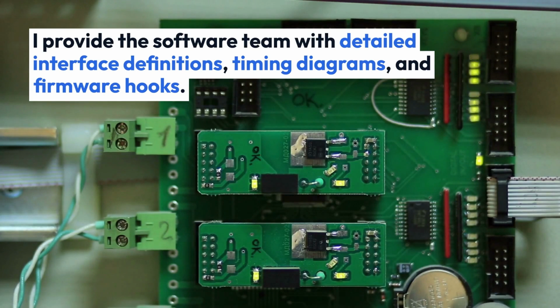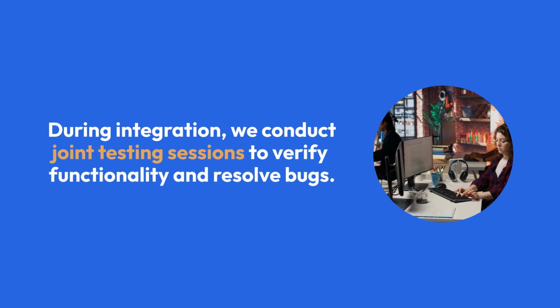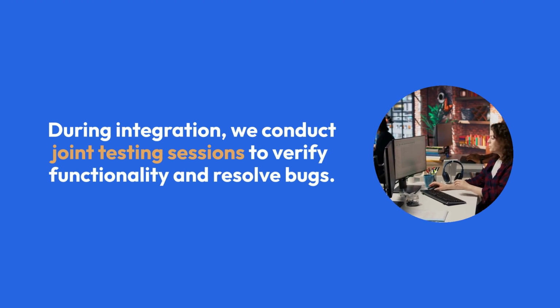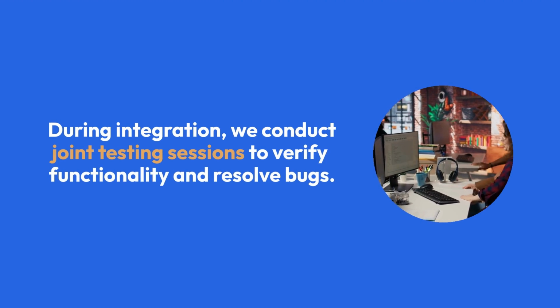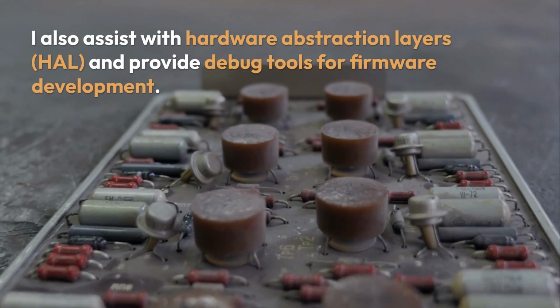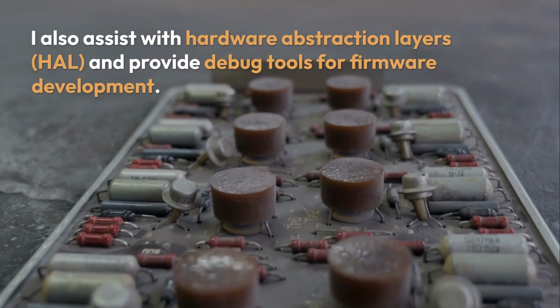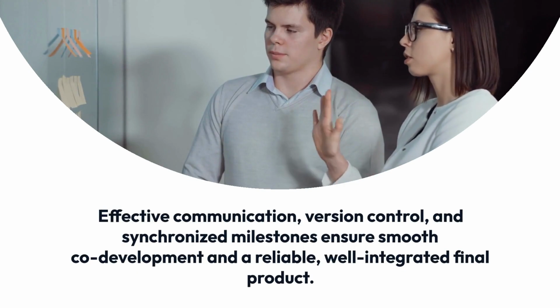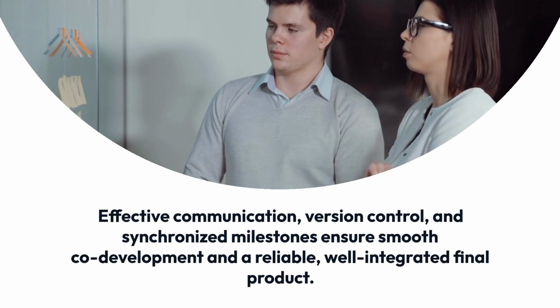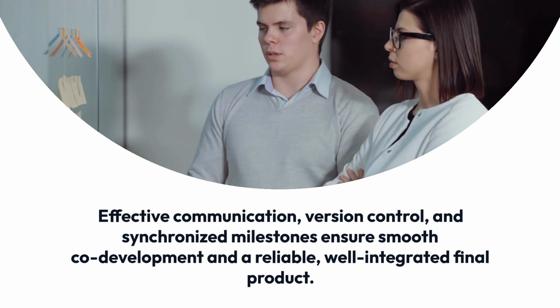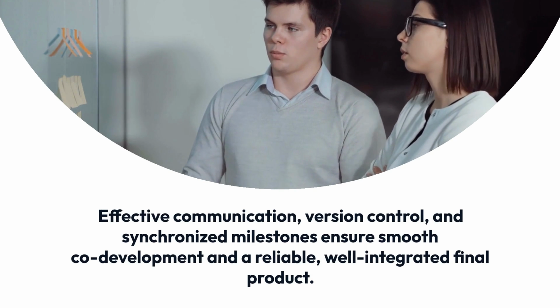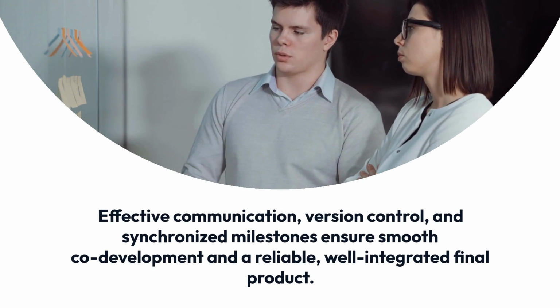I provide the software team with detailed interface definitions, timing diagrams, and firmware hooks. During integration, we conduct joint testing sessions to verify functionality and resolve bugs. I also assist with hardware abstraction layers, HAL, and provide debug tools for firmware development. Effective communication, version control, and synchronized milestones ensure smooth co-development and a reliable, well-integrated final product.